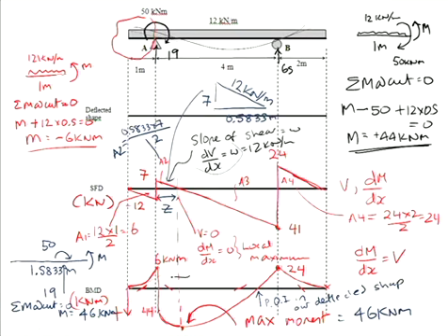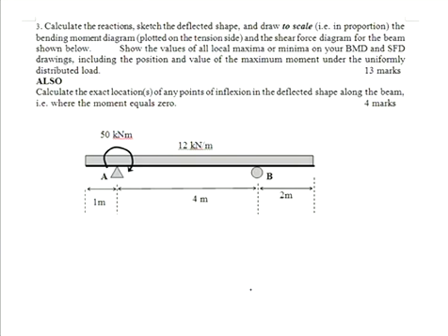And it also means that, because my bending moment passes through 0, we have a point of inflection in our deflected shape. So now when I draw my deflected shape, I have a point of inflection here, so I know I've got tension on the top. Then I'm going to exaggerate it significantly, it comes down, and then I have a point of inflection. Whether you drew that up or down didn't matter, as long as you indicated you had a point of inflection here.